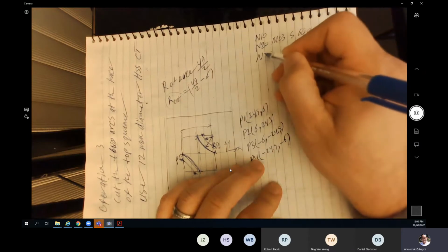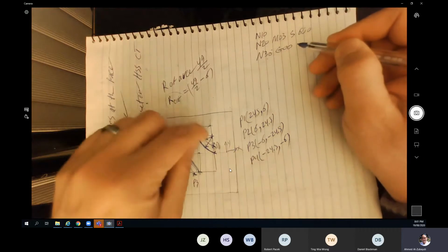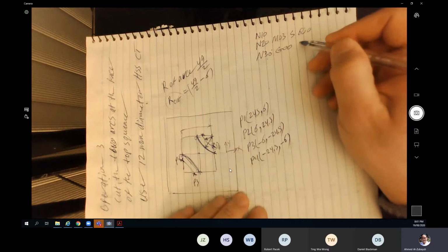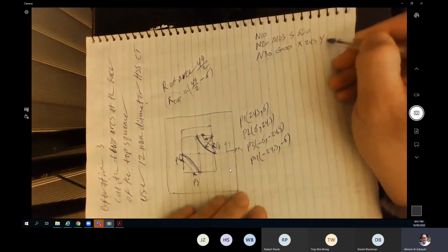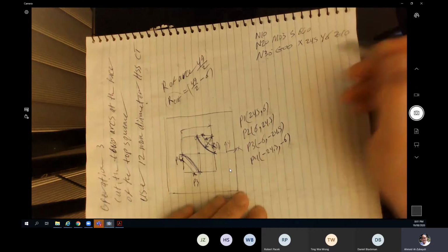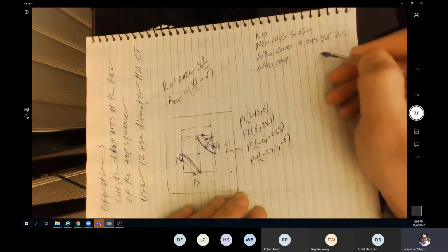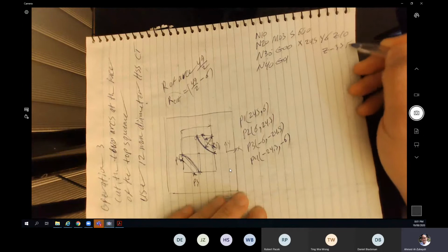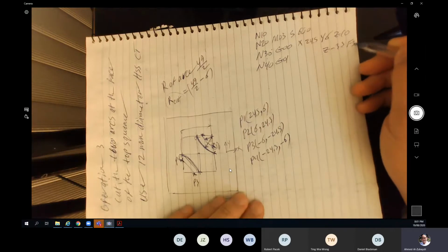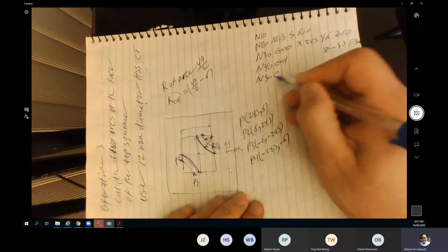The N30 is going to be G00 at the top of point number 1. So the X is equal to 24.5, the Y is equal to 6, the Z is equal to 10. Then the N40 is G01 to Z equal to minus 3.5 with the F of 300, for example. Then the N50 is going to be G0.